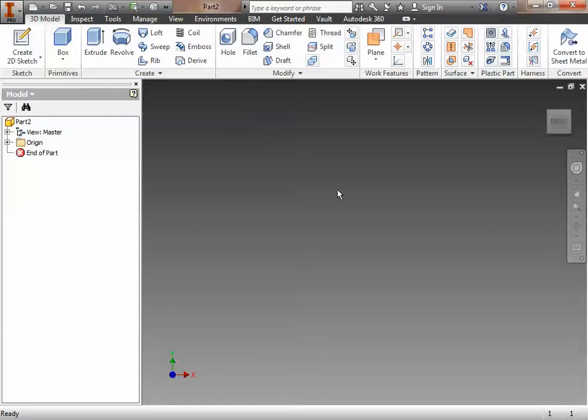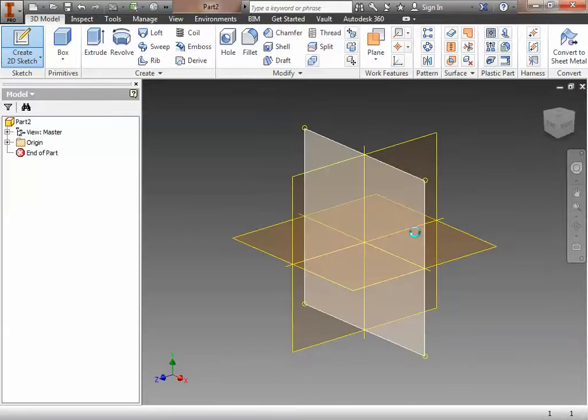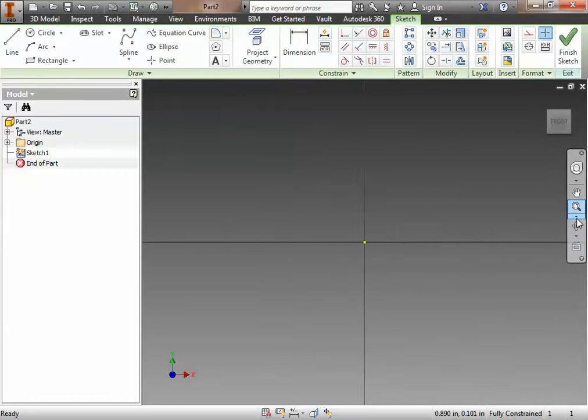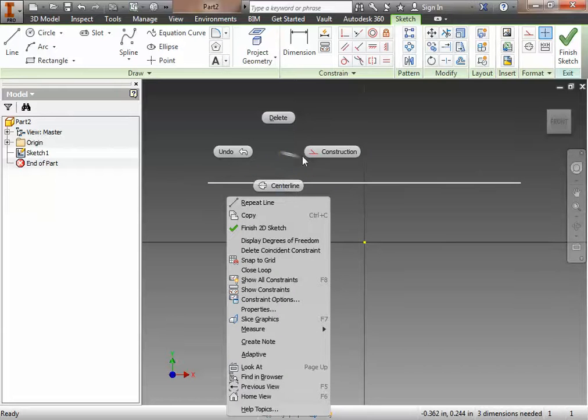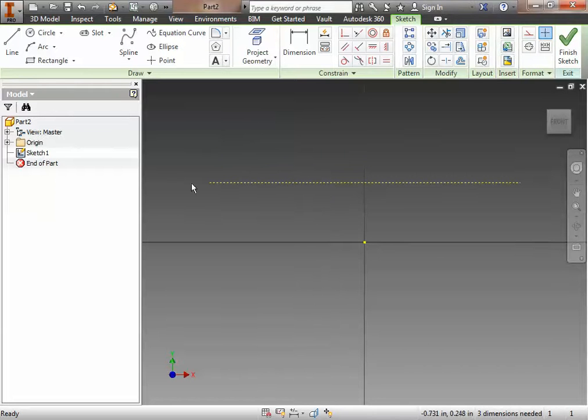It's not terribly bad. The only really hard thing in a sense is that you have a couple of dimensions that you have to figure out mathematically, and the document does kind of walk you through what dimensions you're supposed to need to do it. There are two schools of thought on how to create this button maker handle as far as the geometry is concerned, but no matter which way you go, you need an axis of rotation. So the quickest way to do that is to make a horizontal line and then switch it to a construction line. And we'll use this as our axis of rotation.